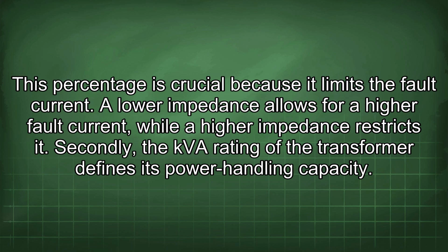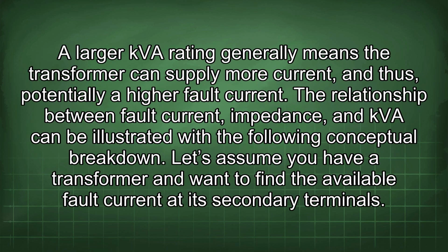Secondly, the kVA rating of the transformer defines its power handling capacity. A larger kVA rating generally means the transformer can supply more current, and thus potentially a higher fault current. The relationship between fault current, impedance, and kVA can be illustrated with the following conceptual breakdown.